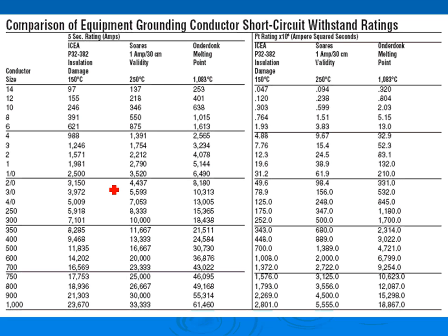Then you get into the equipment ground conductor. Now, what happens to the ground fault? The ground fault is going to go back through the equipment ground conductor. So your equipment grounding conductor could be grossly undersized based on the short circuit in your building, and that's what gives you a couple of sizes. For example, let's look at number 12 again. Number 12 for 5 seconds.